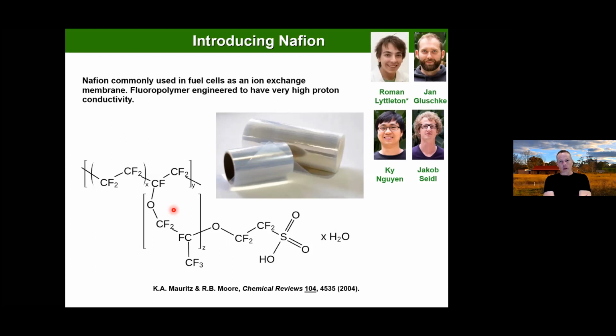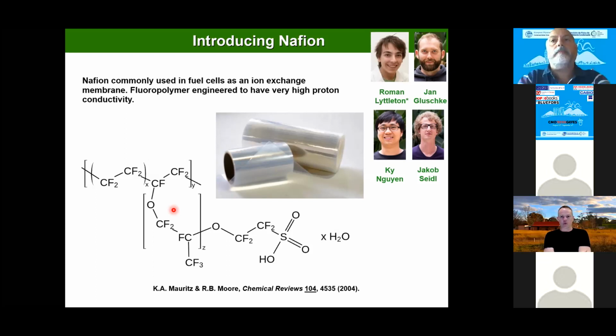So our polyethylene oxide devices would last forever. Like, we pulled out some that we'd made years ago and put them back in to test them again, and they still work. The Nafion devices, unless you store them under a vacuum, they don't survive very long in ambient environments. And that's probably a big issue for Nafion as a material. Ultimately, people might end up having to head towards some sort of middle ground where you have a material that's a bit more stable than PEO from a fabrication perspective and a bit less acidic than Nafion from a biological perspective. That might be a utopia, and that's sort of where we're thinking of doing some work in this.